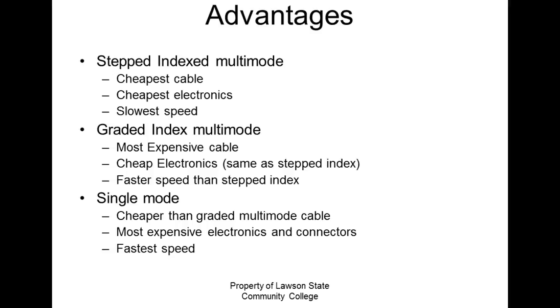Which system is more expensive? Not cable, which system? Which one? This is the most expensive system. This is the next most expensive. This is in the middle, and stepped index is the cheapest system. Now, when we're talking about system, we're talking about not only the end electronics, right? You understand, and the fiber itself, and the connectors that we need to splice them and terminate them.